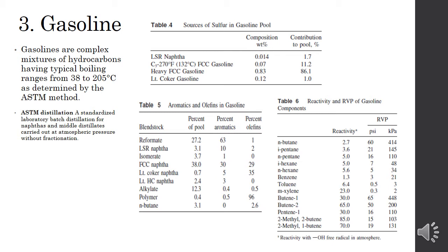The C5 to 88 degrees centigrade fraction means that pentanes are included in the cut, but the C4 and lower boiling components are excluded. The temperature of boiling point end points is approximately 88 degrees centigrade. As a result, it is processed separately from the heavier straight-run gasoline fractions and requires only caustic washing, light hydrotreating, or, if higher octanes are needed, isomerization to produce a gasoline blending stock.